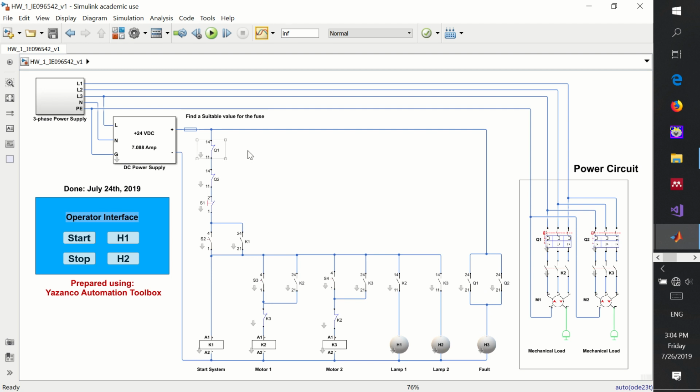One configuration to utilize the safety components in the circuit is appearing right here. Here we are putting both K1 and K2 normally closed contacts in series, since we don't care exactly which one will actually cause the problem, and we need to protect the circuit. That could be associated as well with de-energizing K2. We can rely solely on the protection provided by Q1, but it's good practice to support it by releasing the contacts of the corresponding contactor if they are already connected. So if we are facing any kind of overload, those will be opened and the current will never pass through.